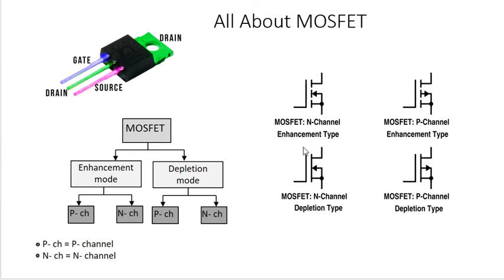And if I ask you this, then you can say this line is continuous, so it is a depletion kind of MOSFET, and the arrow is going inside, it is taking everything in, so negativity, that means it is an N channel depletion MOSFET. I have given this remembering technique just to remember the symbols. This has no relation with the exact theory.